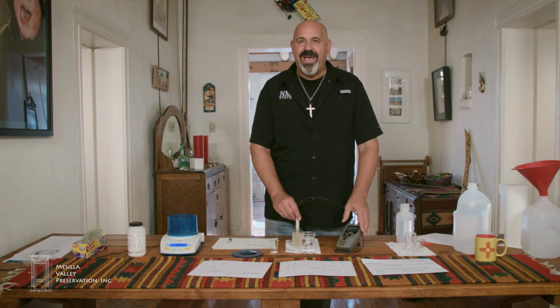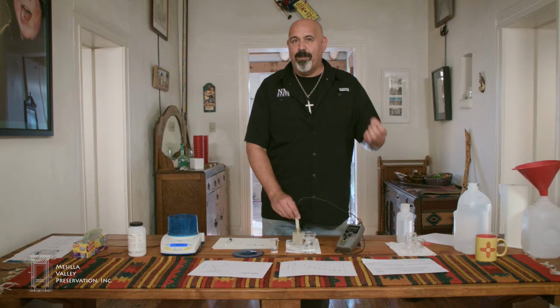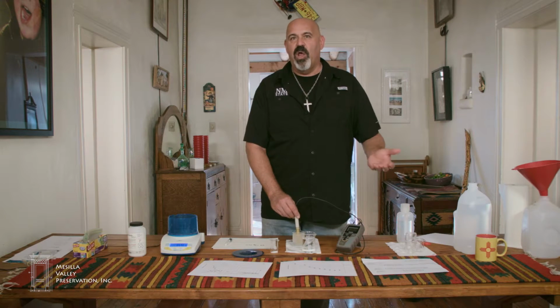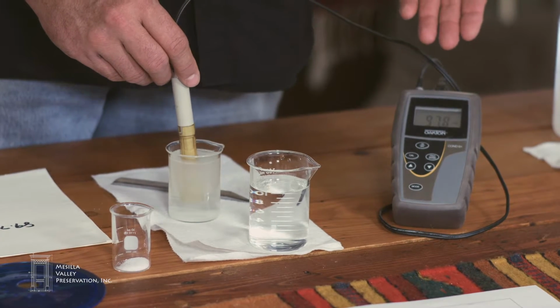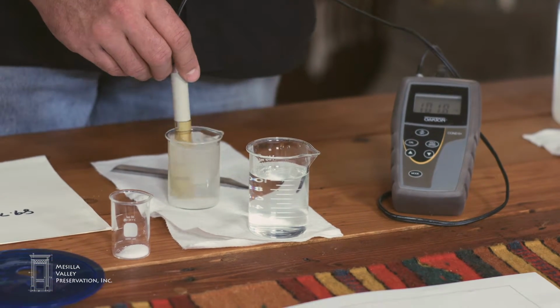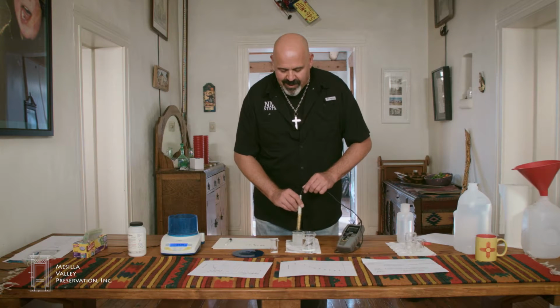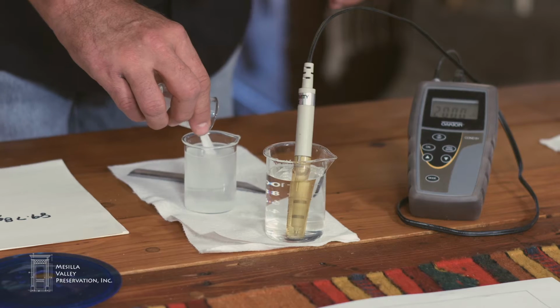The probe itself has a range of up to 200 millisiemens. In that range, it has a linear response, meaning that for a given amount of salt, we get a proportional change in the reading all the way up to 200 millisiemens. So I would really like my calibration point to be close to 200 millisiemens without going over. So this tells me I'm about halfway there. So I'll remove the probe, put it back in my soak solution, add some more salt,